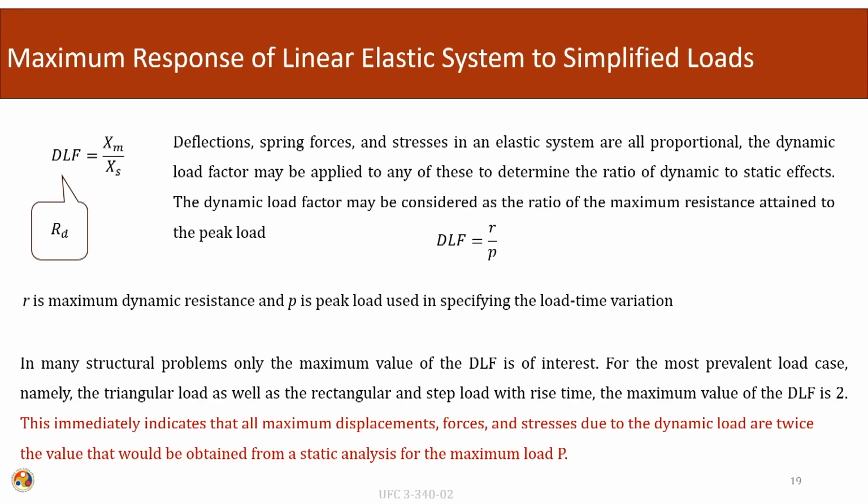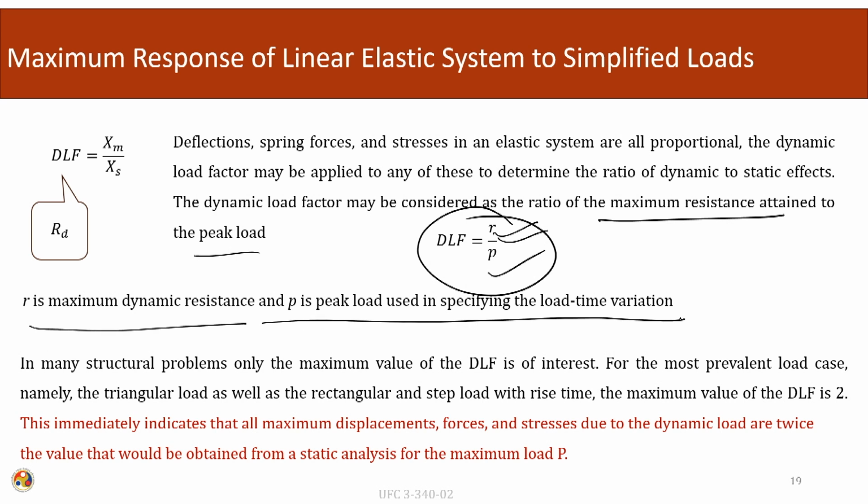So, the maximum response of the linear elastic system to simplified loading. Deflections, spring forces and stresses in an elastic system are all proportional to the dynamic load factor, and this dynamic load factor may be applied to any of these to determine the ratio of the dynamic to the static effects. The dynamic load factor may be considered as the ratio of the maximum resistance attained to the peak loading. So, R is the maximum dynamic resistance and P is the peak load, using a simplified load-time variation.